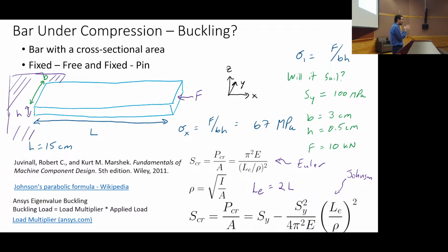So there's an R, right, or a D. And to what power should that be if we're doing to the fourth? Okay, so that's good. Let's say R to the fourth. What else is there? What coefficient then? For a circular cross section. Okay, so you say pi over 32. Ooh, very close. That would be for J.